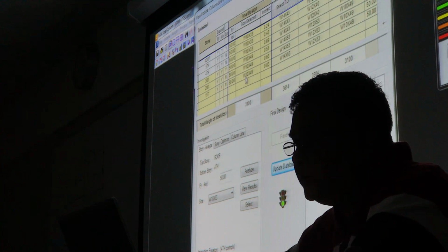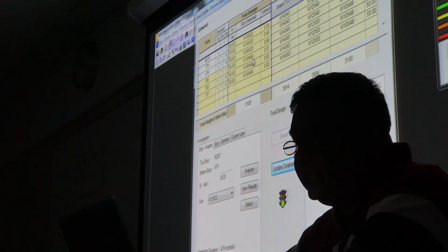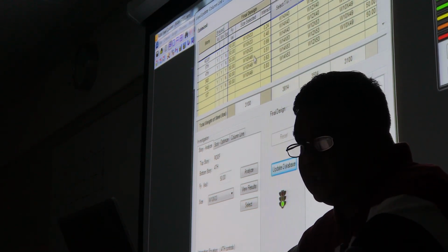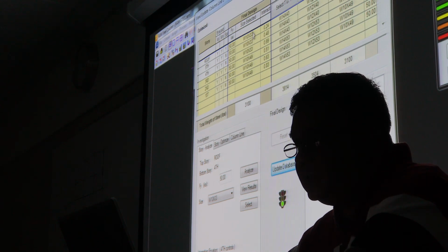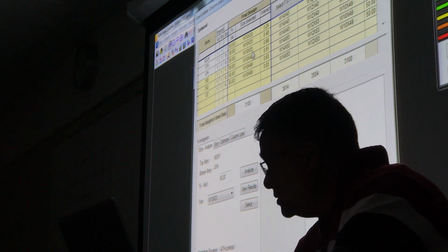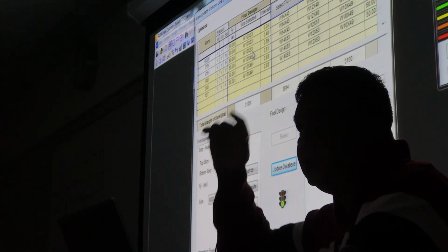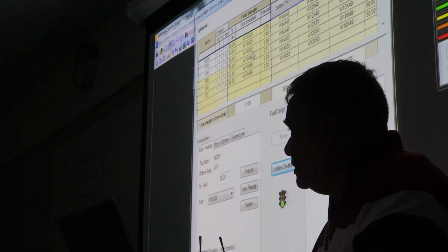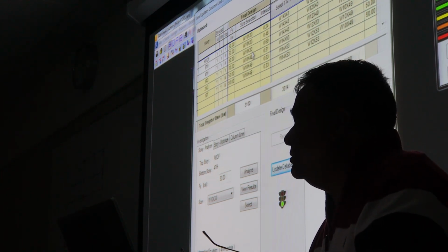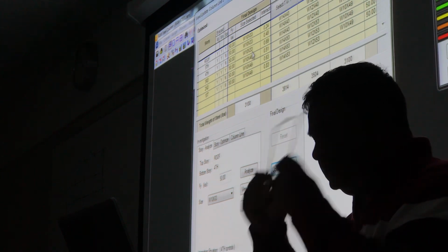And if you see the optimum numbers, the design is W10 by 49 for the first three floors, and the top three floors is W10 by 32. Remember, I added splicing at the third floor. That means change the section after the third floor. What is the advantage? From 49 to 33, so I'm getting some economy.